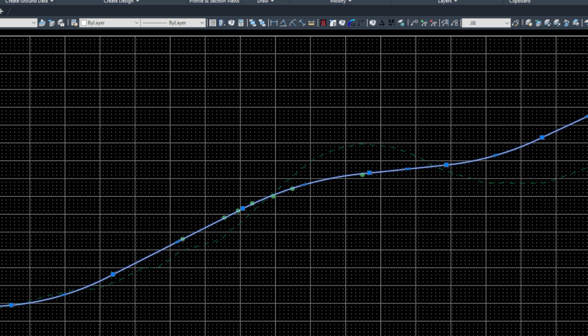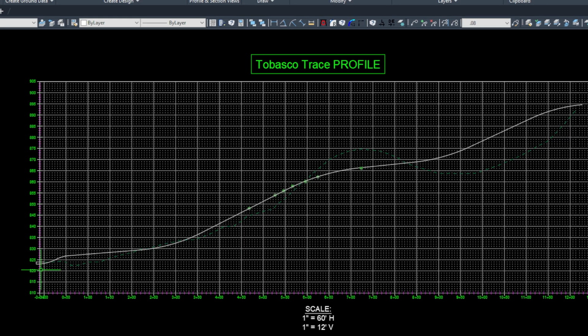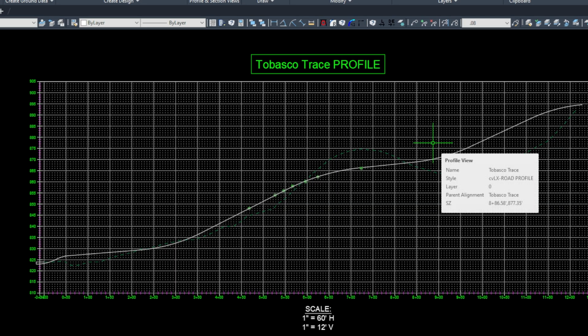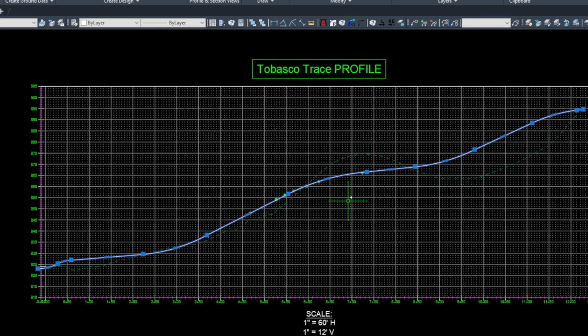We're going to go over the general rule with drawing your vertical curves, which is you want to have it be as smooth as possible. You don't want big weird jumps like you saw in that proposed grade surface that was there before. You want it to be super smooth for these road profiles specifically. So basically you want to have as few vertexes as possible, and then put curves in between your vertexes so that you get nice, gradual curves, and then one straight, linear increase or decrease in slope.